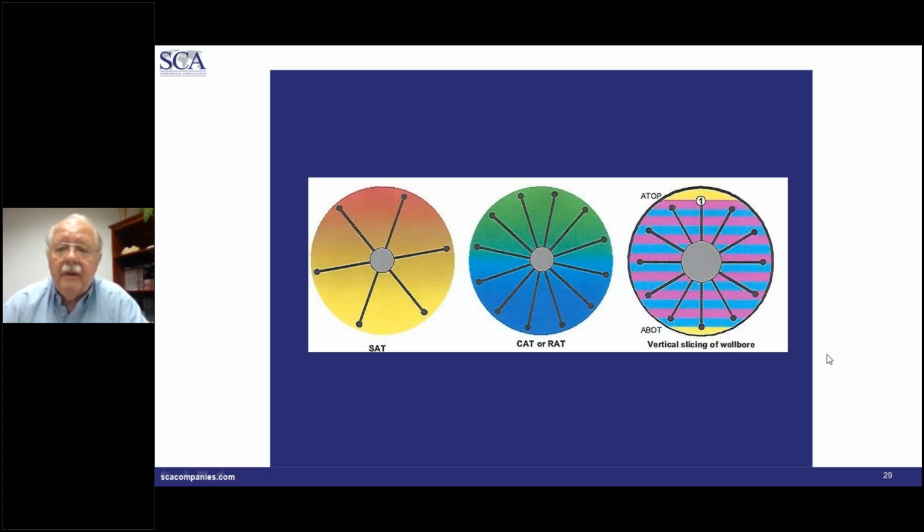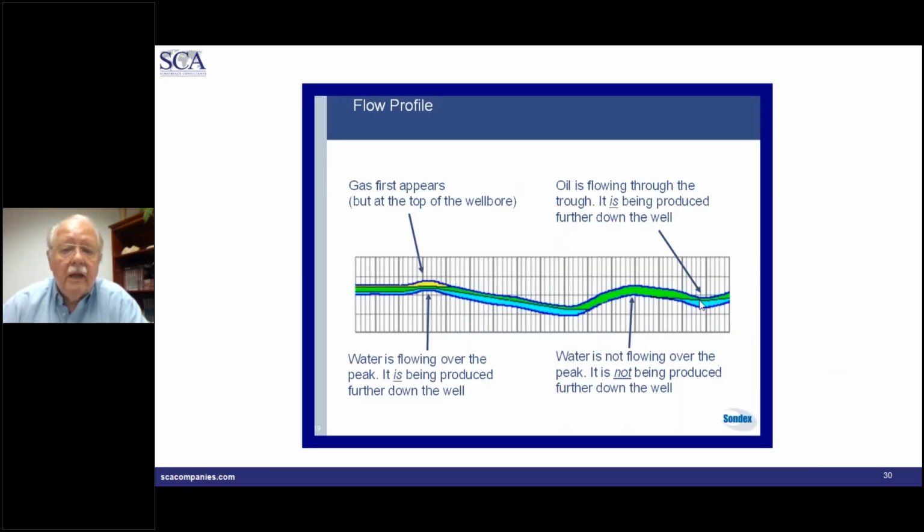One other thing, and then I'm going to be finished. When you look at horizontal environments, you typically have an undulating well like this. The low spots accumulate water, the high spots accumulate gas. These water puddles and gas puddles are in general very difficult to get out. The flow in general will not be high enough to displace these necessarily. So as a result, they affect the flow available, or the area available to flow. So this is why the calculation here is further complicated.